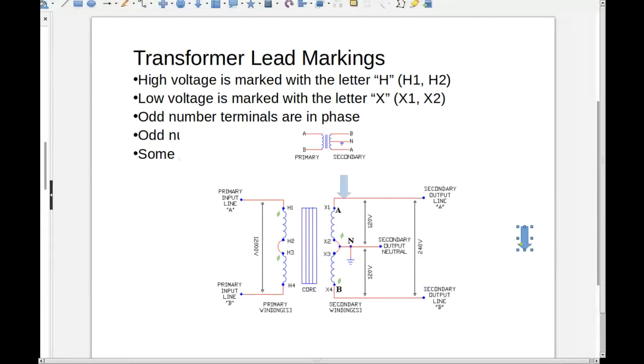But if you run through just half of it, then you get 120 volts, and here I've got a second circuit which is also 120 volts. Now notice the ground here. They've got this connected to ground here. There is a ground connection over on this side, but it's a completely separate ground. So that's the isolation I was talking about.